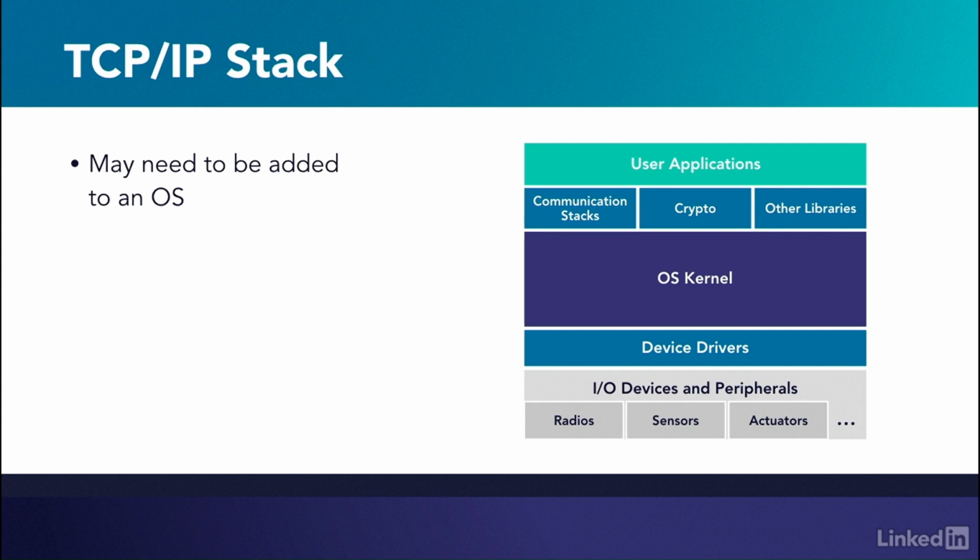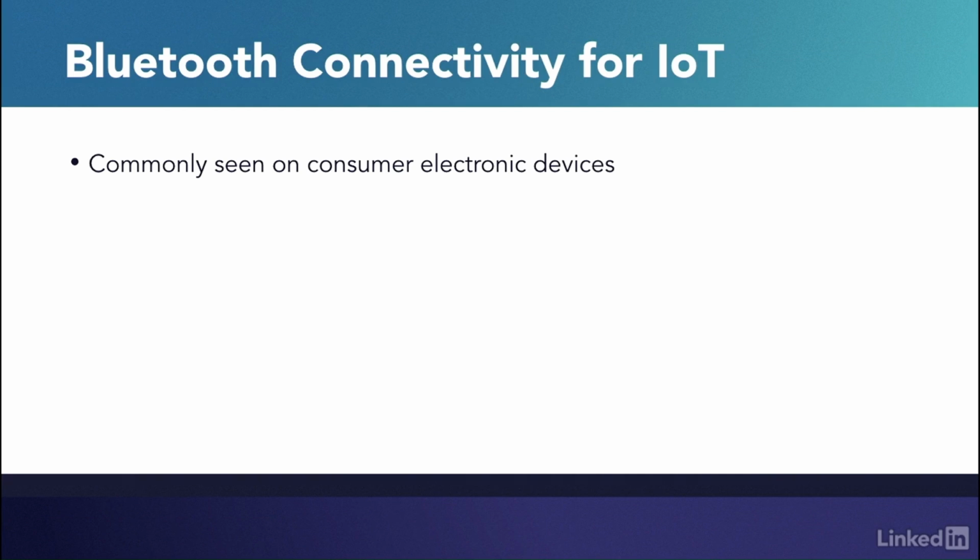for a TCP/IP stack. For a general-purpose OS such as a Linux OS, we can add the support for the TCP/IP stack when setting up the network support using the kernel configuration tool. But for an embedded OS or RTOS, we may need to add such support manually. There are quite a few free and open-source TCP/IP stacks that we can use, such as LWIP, which has been widely used and can be ported to use in various embedded OSs, commonly seen on consumer electronic devices.